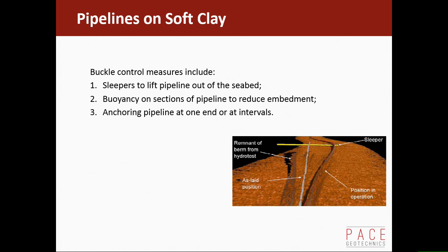And by managing the spacing of those sleepers and lifting it out of the seabed, you're effectively releasing the lateral friction, so it'll try and slide there. By managing the spacing, you know how much the pipeline's going to expand, so you can then work out how far it'll deflect and whether that's acceptable or not.